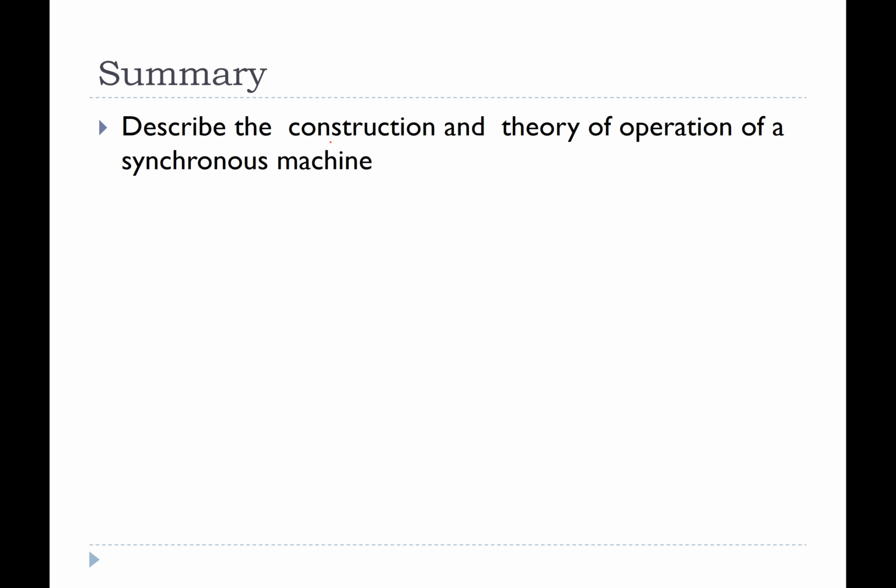So you should be able to talk about the construction of the stator, which is the same as we did for the induction machine, the construction of the rotor, which you could have the cylindrical rotor or the salient pole rotor, and you should be able to describe, if it is in motoring action, the fact that you have the rotating magnetic vector set up by the stator which pulls along the rotor, or if it is in generating action, you have the rotor field set up and you mechanically turn it, and that generates the EMF in the stator windings.